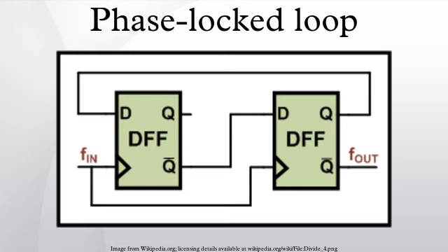Typical trade-offs are: increasing the bandwidth usually degrades the stability, or too much damping for better stability will reduce the speed and increase settling time. Often also the phase noise is affected.